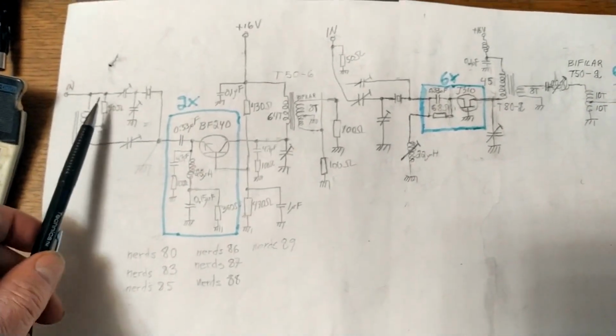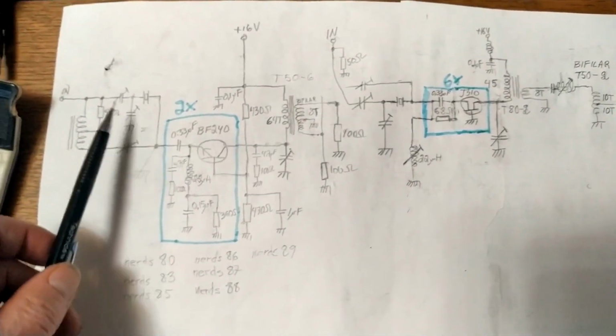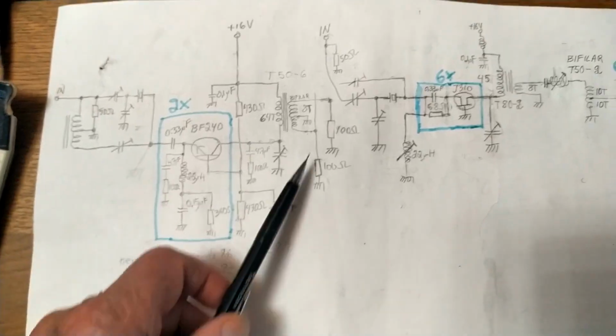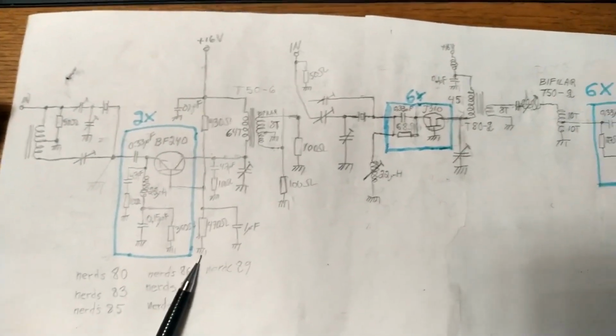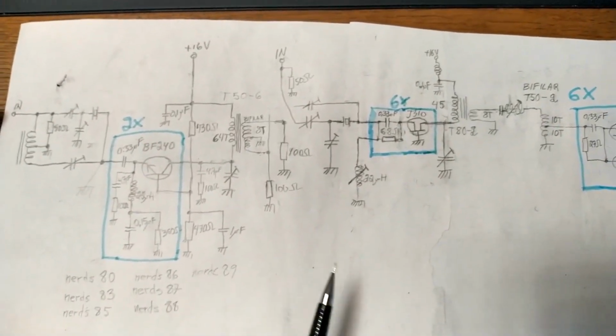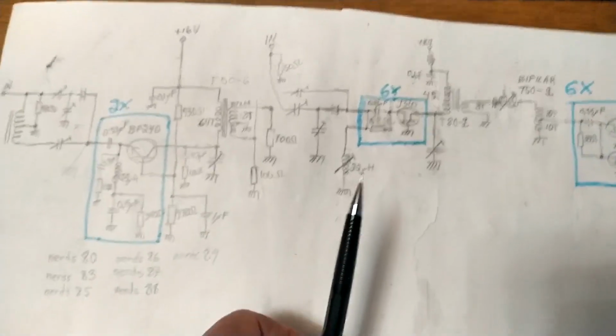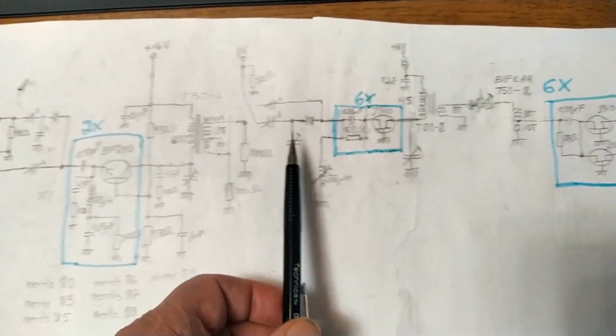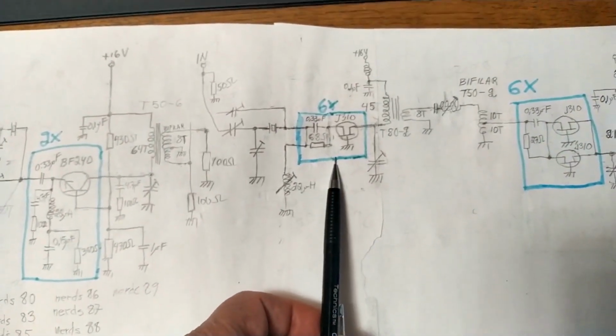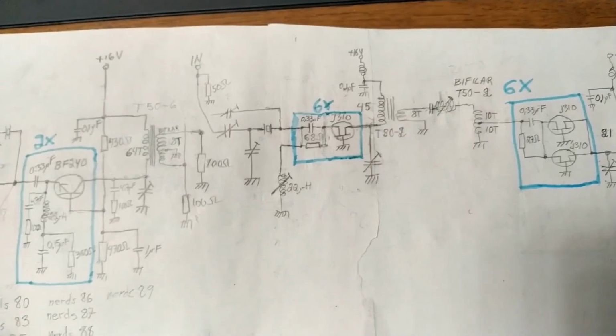First is one amplifier stage with a crystal filter, which is not in use now and hasn't been for a long time, because first I want to have good performance while using only one crystal. So the input is here, and then there are 6 parallel junction FETs, J310.